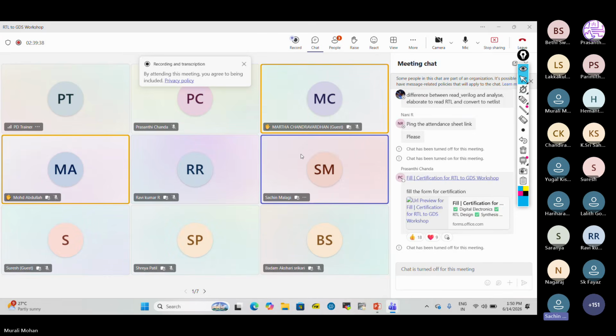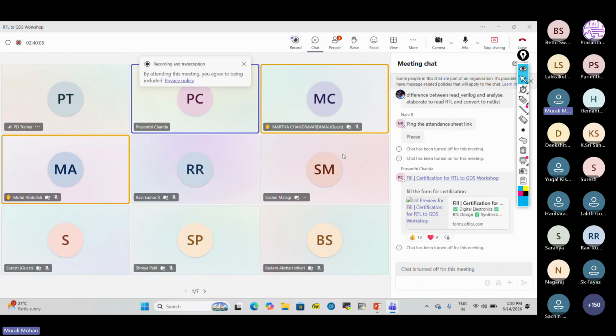So for this macro placement, should we follow the hierarchy, or can we distribute the macros? No, we want to follow the macro hierarchy as a grouping. Macros that have connections, you want to place near each other only. If you distribute them, there will be a chance of crisscross connections, and then the routing will be impacted. Indirectly, it will affect your timing and everything else.